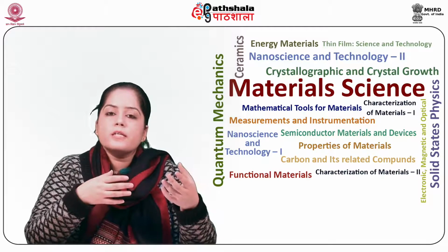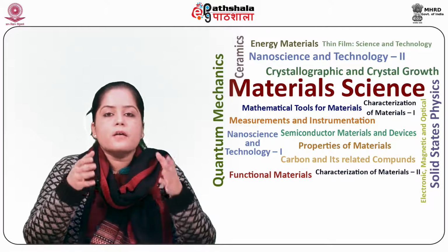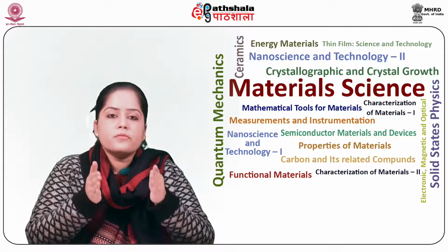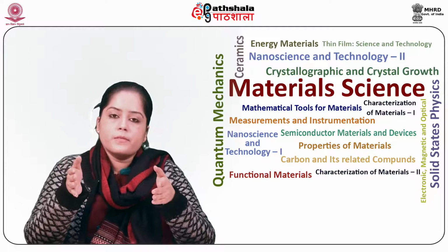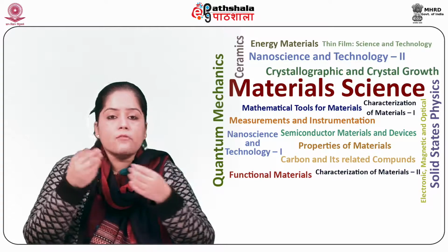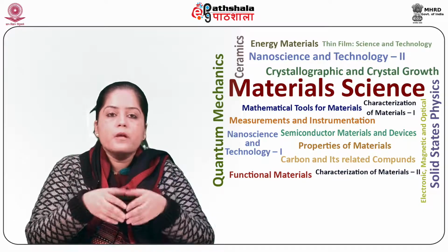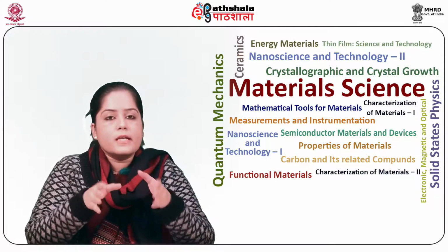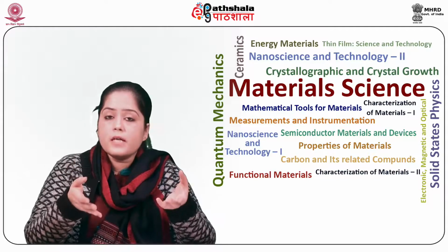Group 3 impurity elements such as boron, which use up the electrons, are referred to as acceptors because they accept some of the electrons already in the silicon, leaving holes. Similarly, group 5 donor elements such as arsenic and phosphorus provide electrons. Silicon that contains a majority of donors is known as N-type, while silicon that contains a majority of acceptors is known as P-type.